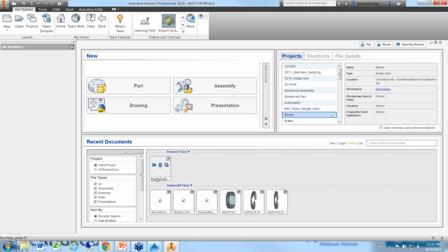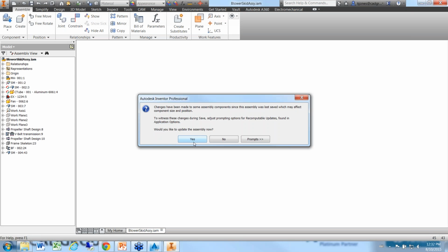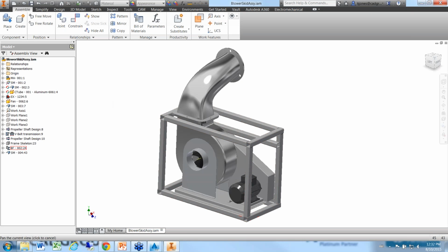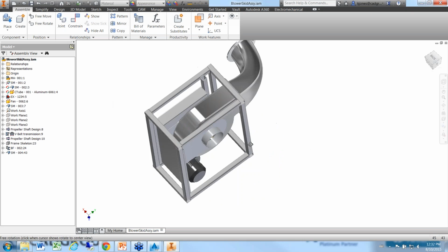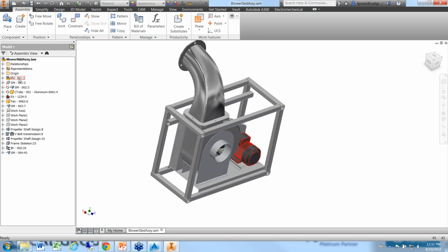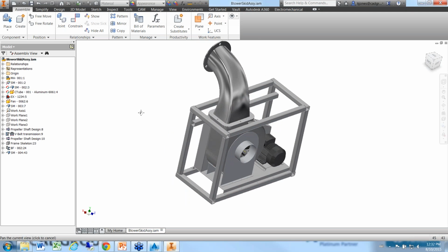Application. So I'm going to start off in a small assembly inside Inventor. Okay, so I've just got a little blower frame assembly in here. From the blower frame, essentially all I need to do, as I talked about, is that Inventor has a large multiple part scale. So if I export the SAT straight from here, I'm going to end up with lots of multiple components inside Advanced Steel. So you want to give them a more simplified design.